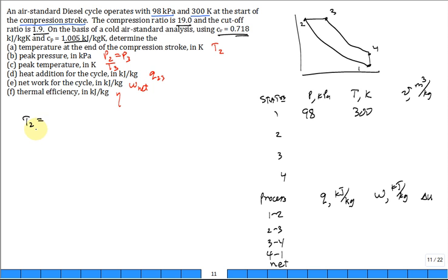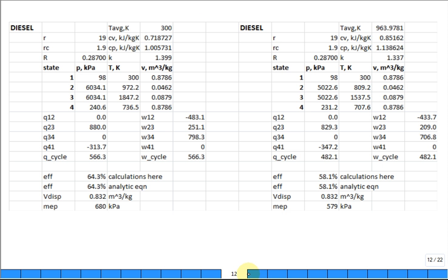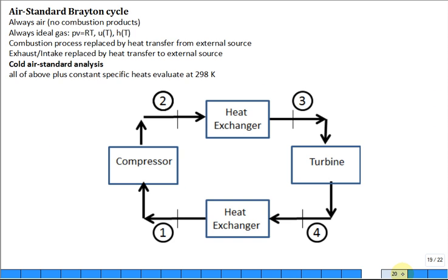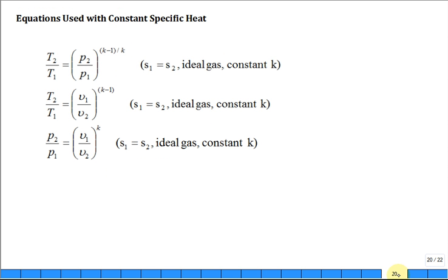Which is it? I know that they're, let's see if I have the, oh, come on now. Here. Right? So if I have an ideal gas undergoing isentropic process with constant specific heats or constant ratio of specific heats, which implies the same thing, then if I want to get the T2 over T1 related to P2 over P1 or T2 over T1 related to V1 and V2, etc. Use this one right here for that first process, right?